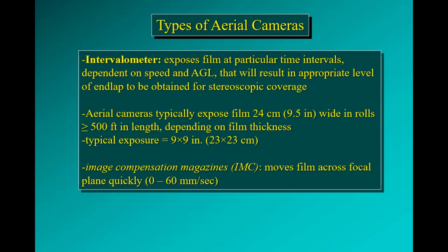So we want a certain sufficient amount of overlap from one successive aerial photograph to the next along the flight line in order to have stereoscopic imaging, and then based on those data that are being collected, we can derive a variety of products based on photogrammetric analysis. Aerial cameras typically expose film that is 24 centimeters or 9.5 inches wide in rolls of